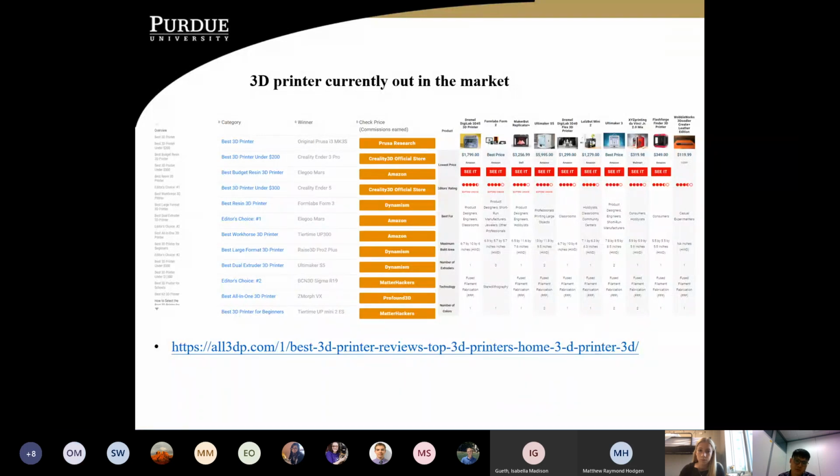The investment you put into buying a $300 3D printer will do the printing eventually, but a lot of it you have to do DIY. For example, putting in the filament by yourself, or if it's printing a kludge, would it stop by itself? A lot of these low-end 3D printers will continue printing, and therefore you probably have to stay there all night to watch. However, some of the 3D printers up to $1,000 are smart enough to detect that and stop. Now, it's debatable, as you can later upgrade those $300 low-end printers to a certain scale so that they are smart enough to stop.